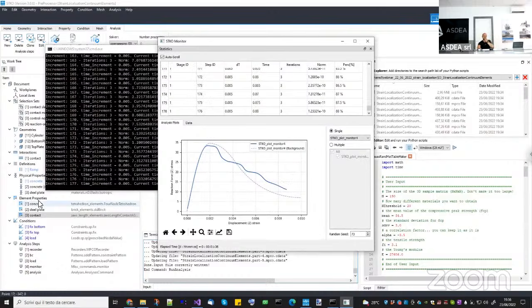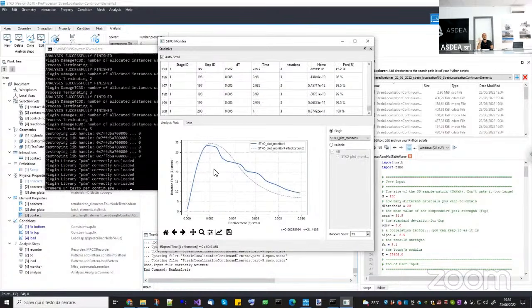But when you are doing solid modeling, the boundary condition is very important. Even if you make a wrong prediction on the friction coefficient of the support, it can give you a completely wrong result. Now it is fine. Okay. Now I use the correct regularization, a correct boundary condition to resemble the experimental test, and now it is fine.